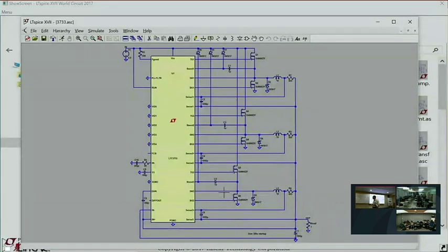It supports synchronous rectification, so there's 2 MOSFETs per phase. The thing supports remote voltage sensing. That is, there is an op-amp printed on the same silicon as the controller to support remote voltage sensing. And you have to hook up its feedback network, and there's no option not to use the op-amp. You have to hook up that op-amp to evaluate the part, try the thing out. There's still an error amplifier in its compensation network. There's a DAC to program the output voltage.